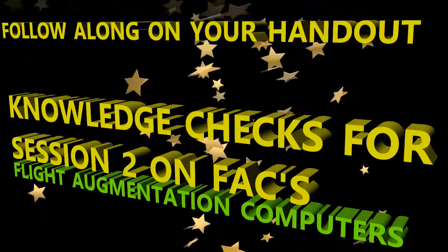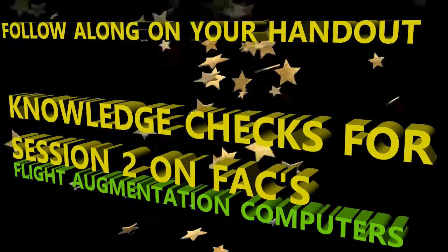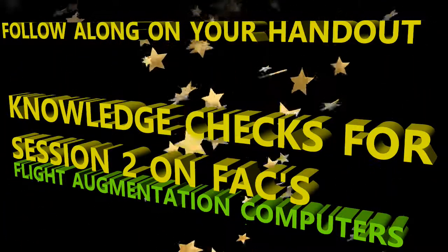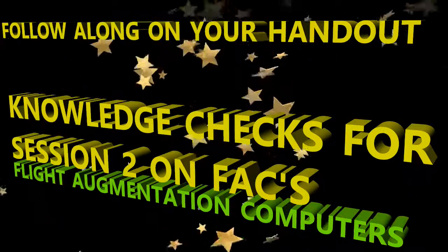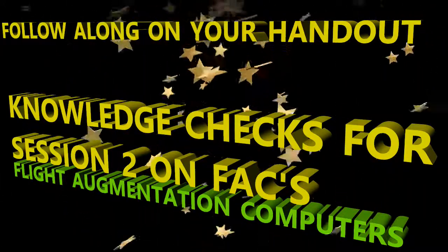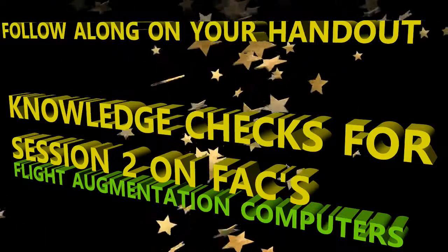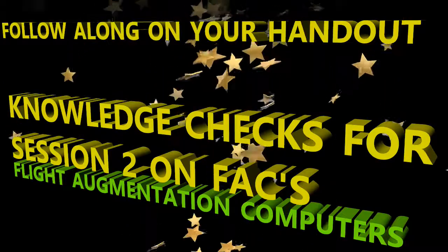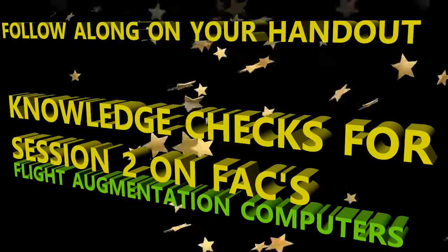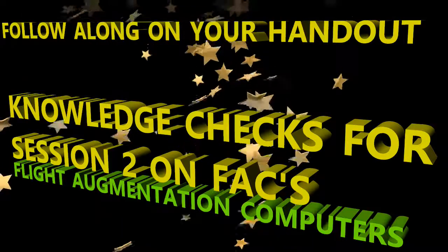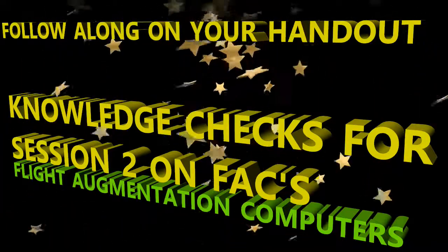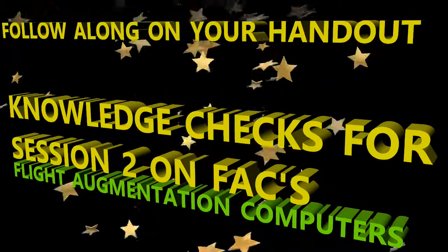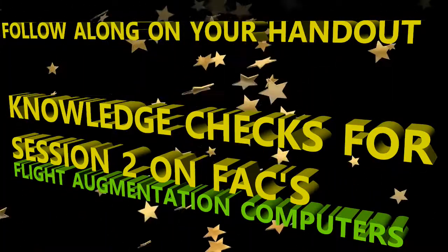Name 2 component failures that will cause a loss of alpha floor protection. Here are your 2 choices. Number 1, the combination SFCC1 and SFCC2 failure. That's your slat flap control computers. Or is it from SFCC2 and FAC1 failure? Okay, it's from the latter. If you have SFCC2 and FAC1 failure, then you're going to have a loss of that protection of alpha floor.